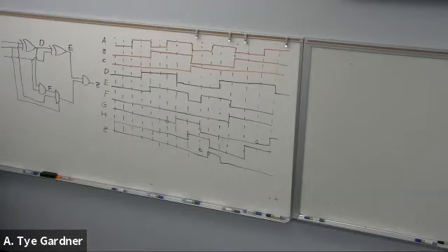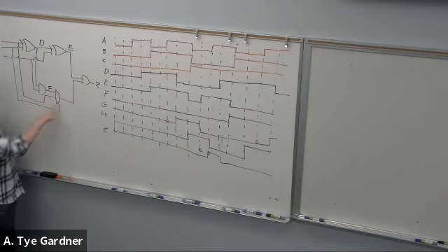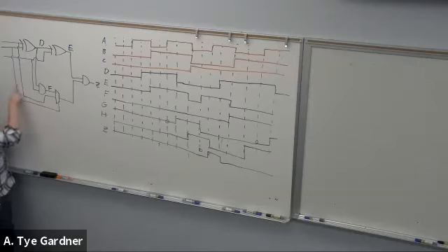It's just that you have to really think about what is happening and make sure that you set up the F node before you do this node, because you have to know what F is doing when the select chooses. If B here was 0, then it takes F, but if B is 1, it's taking A, and it's just functioning as a pass through. And I might keep it simple and say even this delay is 10 nanoseconds.